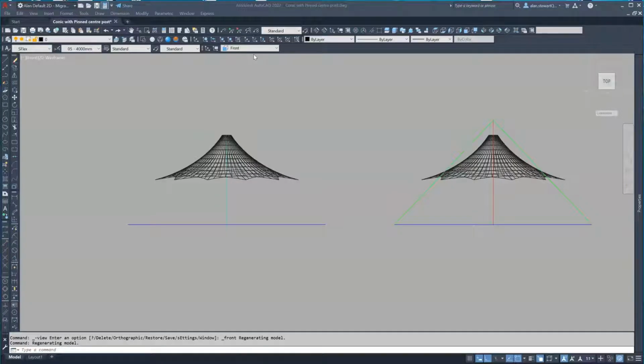In this video, we're going to perform an FEA analysis on a conic structure configured in two different ways. In the first example, we'll have a pin-based pole with all of the perimeter posts restrained, but the top of the center pole allowed to move. And in the second model, we have a pole which projects above the bail ring and is restrained with cables